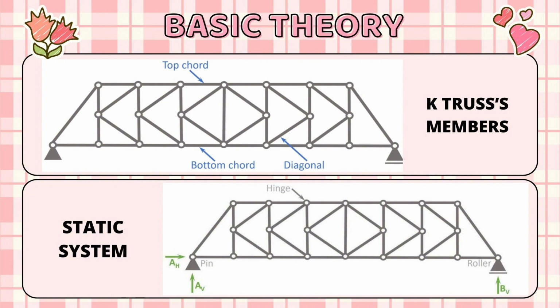Next, K-truss with fixed and hinge connection. This is the most realistic static system, because the top and the bottom chord might be delivered in one piece, meaning that they are constructed continuous and the posts and diagonals are attached to them. The rafters basically turn into a two-span continuous beam, which means that the static system is no longer statically determined. This means that advanced methods of FE programs need to be used to calculate the internal forces like moments, normal and shear forces.